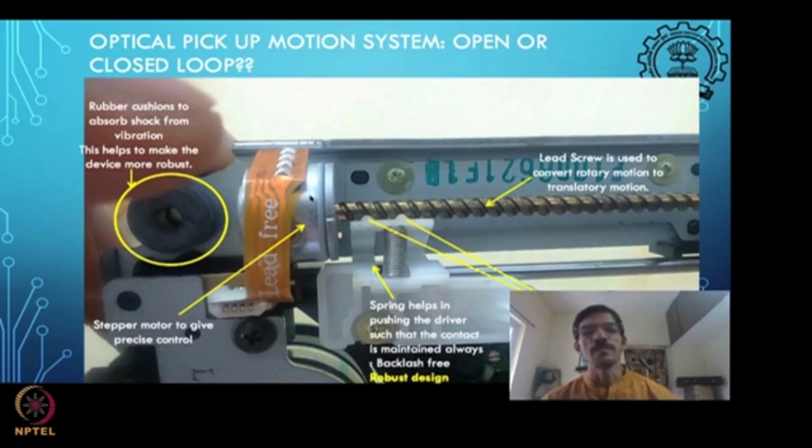Normally we can identify, based on these terminals, what kind of motor it will be. If you have more than two terminals, it's not going to be a servo motor. A servo motor will typically have two terminals, plus and minus, coming out, but this seems to have more terminals. So this is like a stepper motor here.